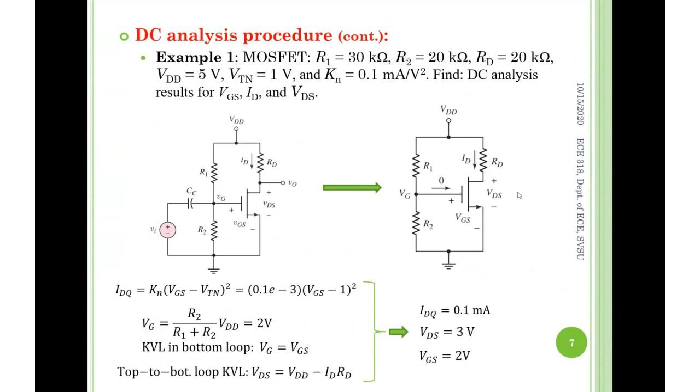When the transistor turns on more, like VGS increases from the AC, then VDS would start to get smaller. That's right, you're talking about AC. I'm sorry, I thought you were talking about DC. AC is swinging there. The VDS would decrease as you increase VGS, right? Correct.